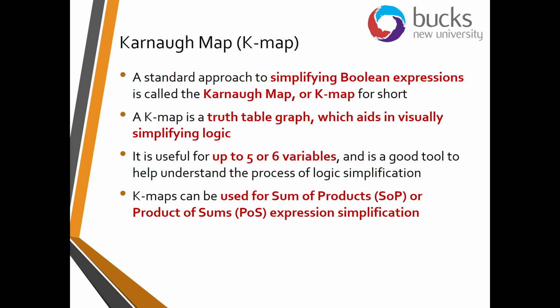So this is good for that level of variables, but for bigger circuits or more inputs, it would get too unwieldy. That's where your theorems and your De Morgan's law really come into their own. It's a good tool to help understand the process of logic simplification, and K-maps can be used for both sum of products or product of sums expressions to aid the simplification.